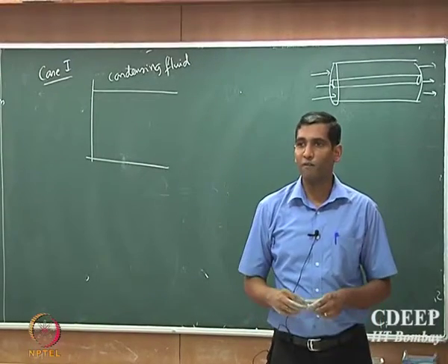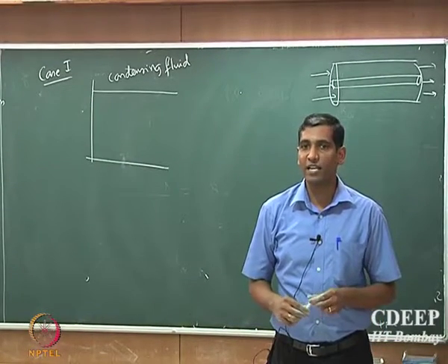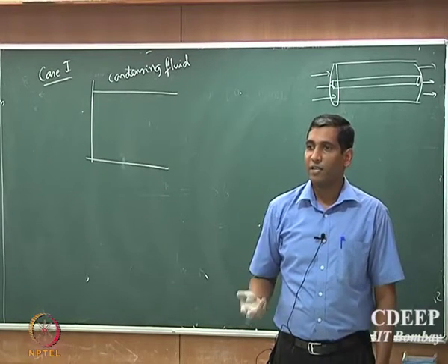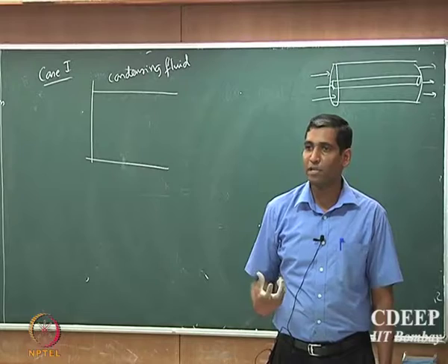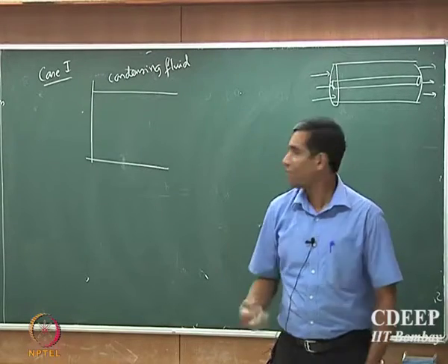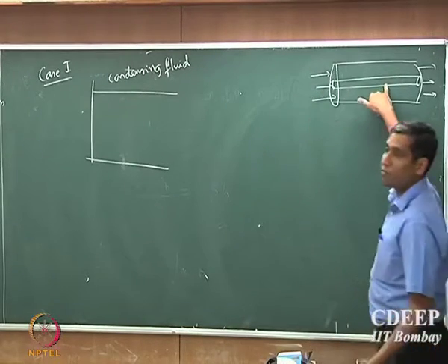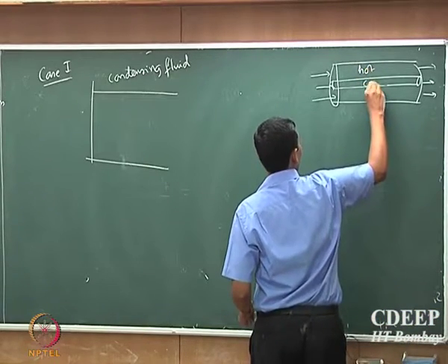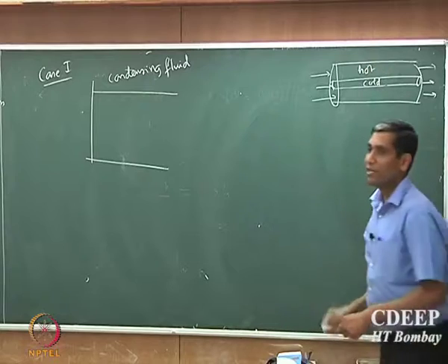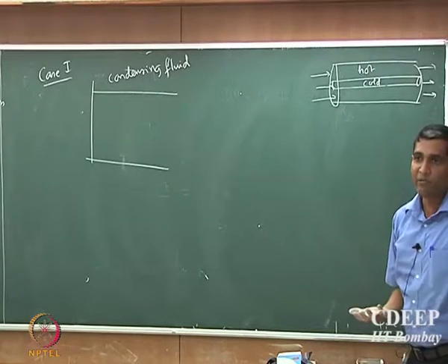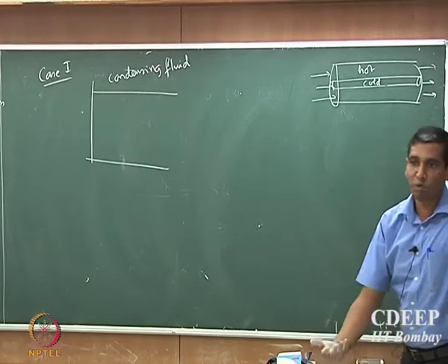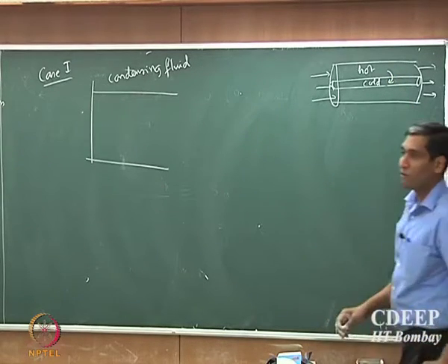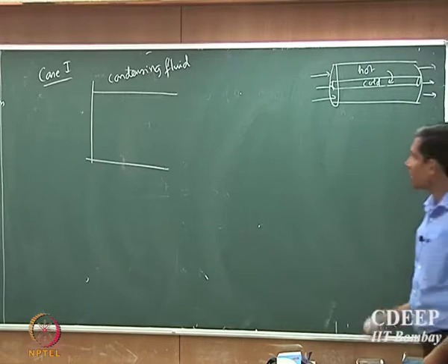The temperature of the fluid inside the heat exchanger will remain approximately constant, because it's the latent heat which is being used to heat up the fluid flowing through the internal tube. The hot fluid liberates the latent heat by changing its own phase, and that heat is transported to the cold fluid which is being heated up.